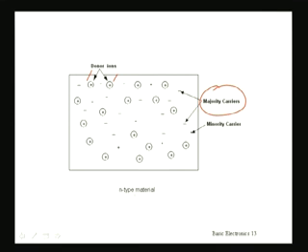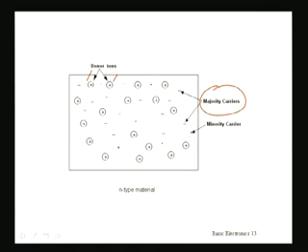So in an n-type material, the majority carriers are electrons, but there will also be, in less numbers, minority carriers, which are holes. These holes will be from this intrinsic material that is coming. So if n-type material is considered, altogether we will be seeing majority carriers as electrons, minority carriers as holes, and immobile ions which are positively charged, the donor ions. They are there. This is the structure of an n-type material.